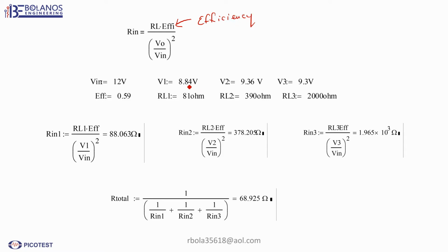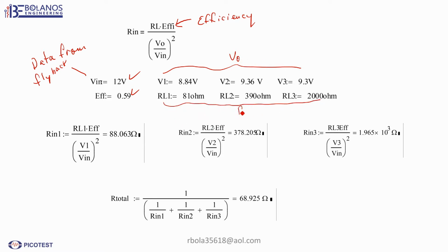So you can say that you have a negative resistance. You can think of it as a small signal R in. So that's where the concept of negative resistance at the input of a power supply comes from.